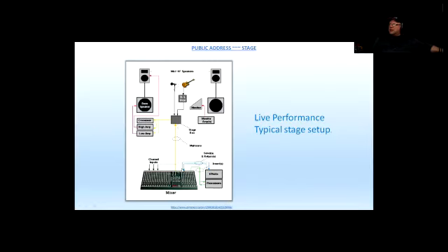Now, another way of doing the monitor mix would be having a stage box that would be a split signal box. So every channel that goes to the stage box is being split. Half of the signal goes to the front of the house mix, and half goes to another mixing board, which is not here, that can be just like the other one, and could be backstage.